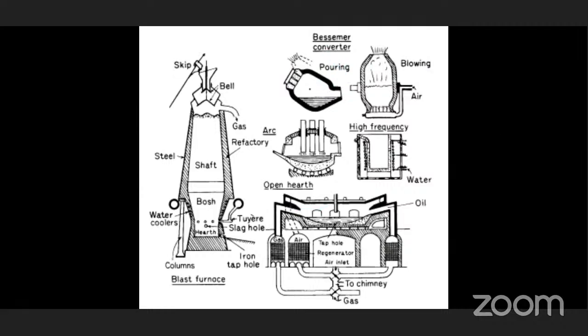Then the composition of pig iron for this process, how it is going to be, and what are the things that we are seeing here. About the furnace we have seen. The Bessemer converter we have to see. So this is a Bessemer converter. It contains the lining, the shell, the trunnion, the blast pipe, and the tires. So these things are the tires. And air will also enter inside it. These are the things required for the Bessemer converter.